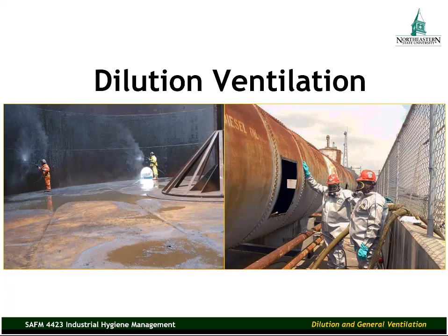All right, we've been talking about local exhaust ventilation. And again, local exhaust ventilation is where you're sucking up the contaminant at the source. You've got a canopy or some type of hood right there at the point where the contaminant is being generated. In some cases, the system is actually connected to the tool that's sucking up the contaminant. So that's really the gist of local exhaust ventilation. Collect the contaminant at the point where it's generated.